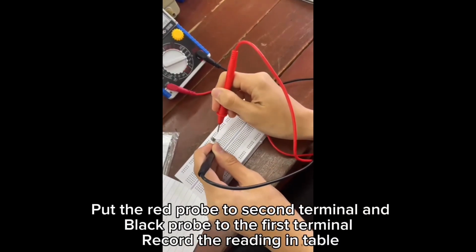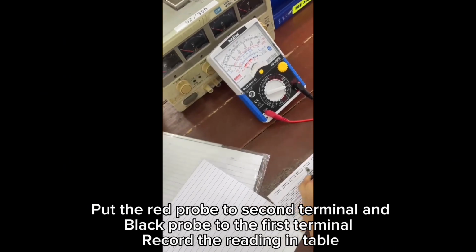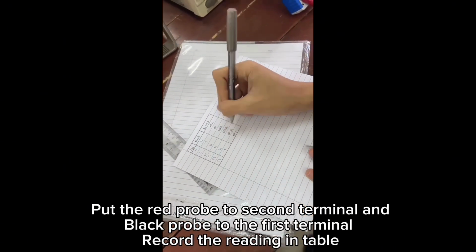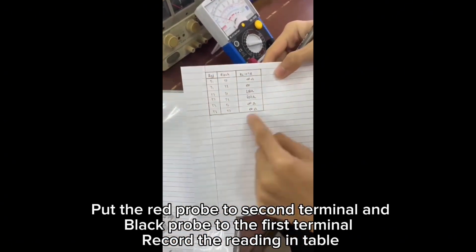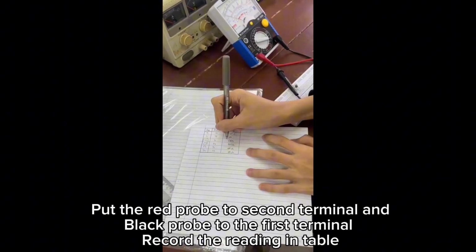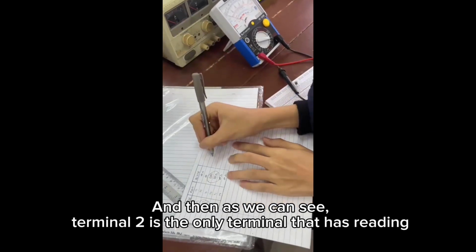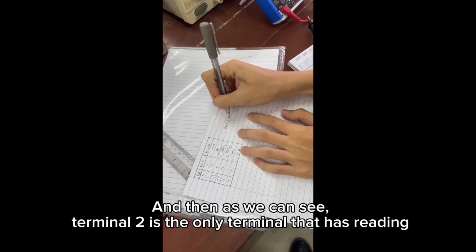Put the red probe to the second terminal and black probe to the first terminal and record the reading in the table. And then, as we can see, terminal 2 is the only terminal that has reading.